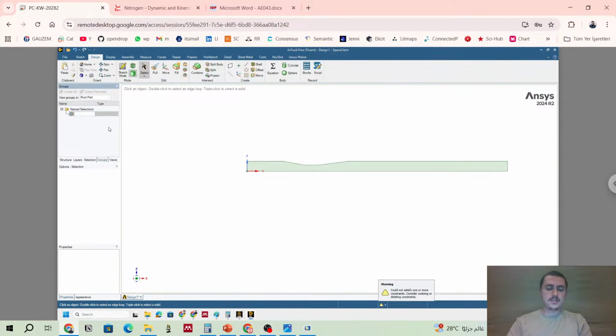Okay, this is the axis. There are some words, if you use them: axis, inlet, wall, outlet. Fluent will understand it automatically and define and put the boundaries there. For example, this is my axis. I want to make Fluent understand that this is my axis, which is being revolved.